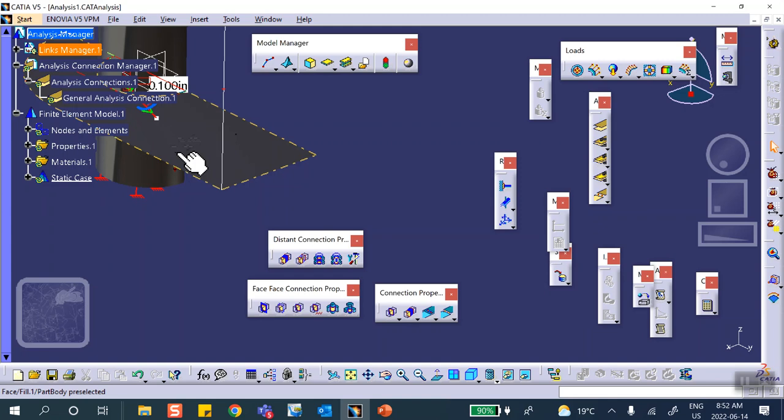Now we can do it to point because it doesn't matter, point and point, rigid, okay, fine, no problem. But when you do a line to surface and make it rigid, this is going to be rigid, this is going to be rigid, means that these stay put. They don't do anything. And these are things you can try. Try it before you take my word.